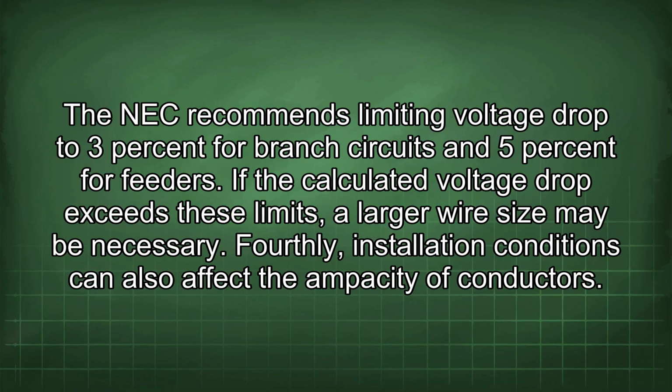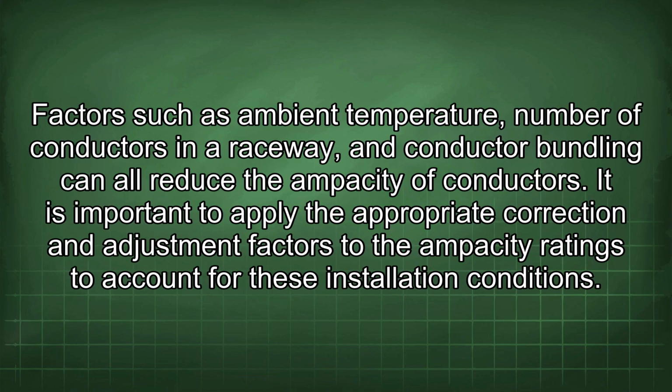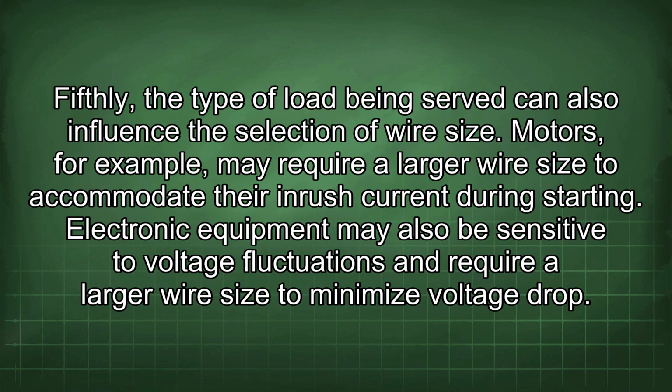Fourthly, installation conditions can also affect the ampacity of conductors. Factors such as ambient temperature, number of conductors in a raceway, and conductor bundling can all reduce the ampacity of conductors. It is important to apply the appropriate correction and adjustment factors to the ampacity ratings to account for these installation conditions.